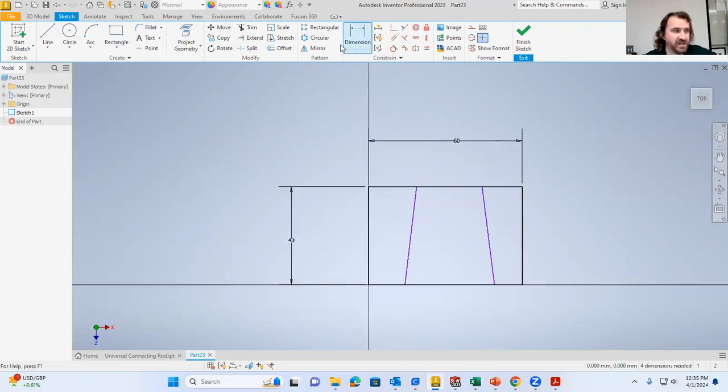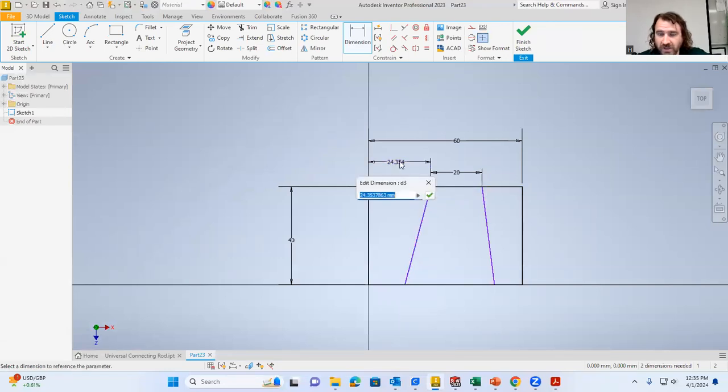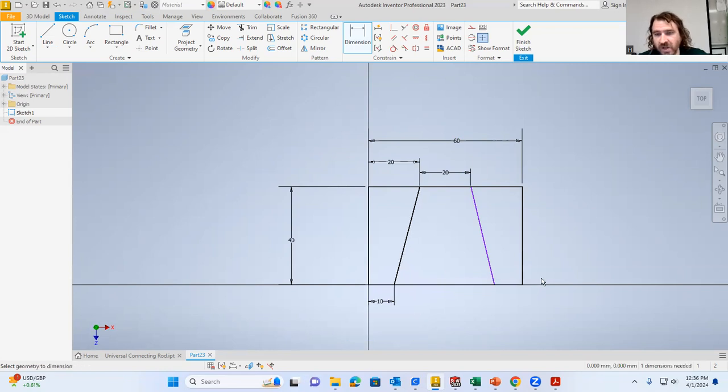So the easiest way to dimension this is to dimension the beginning point of these lines. How far away are they from the whole thing? Well, this to this point here, we're told this is 20 millimeters. And everything being equal, this would also be 20. And so we have 20, 20. This is also 20 because of the value of 60 that's here. Then we look at the bottom here. The smallest dimension that we're actually given is 10. So that's exactly what we need to have to these two points at the endpoints of these lines, 10 millimeters from the edge to the end point of those lines.